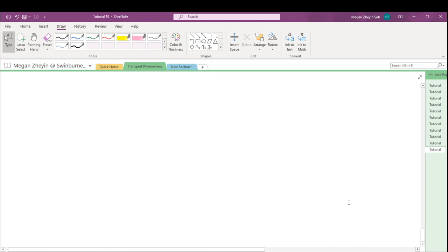We have your rate of mass in at Z, same thing, U_0 A C at Z, minus U_0 A C at Z plus delta Z, minus your rate of gas consumed in the catalyst, which is given by 1 minus epsilon, 3 over R, J_P, A delta Z, equals 0.